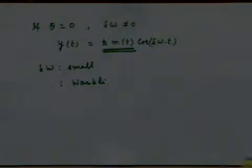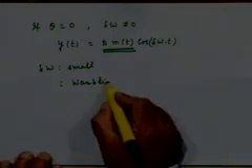The amplitude will go up and then come down and then go up again and so on. You will therefore hear a distorted version of the actual signal, and the kind of distortion that results is called wobbling distortion. This is a wobbling phenomenon, amplitude going up and down. This is called the wobbling effect.